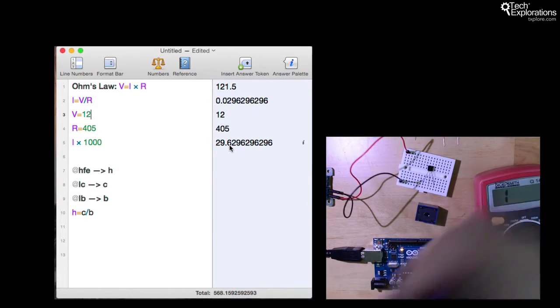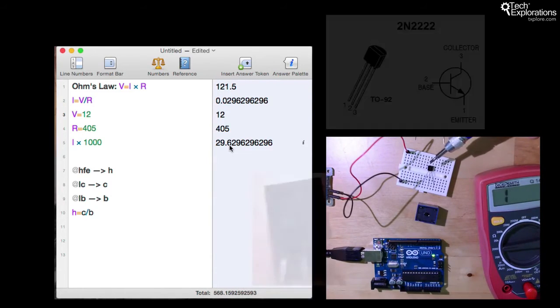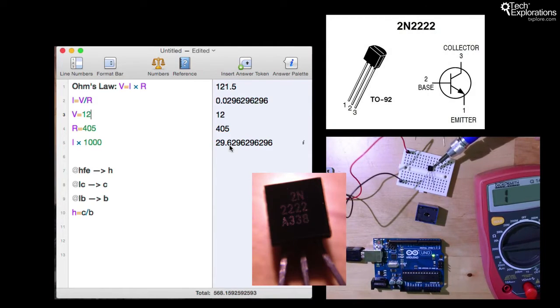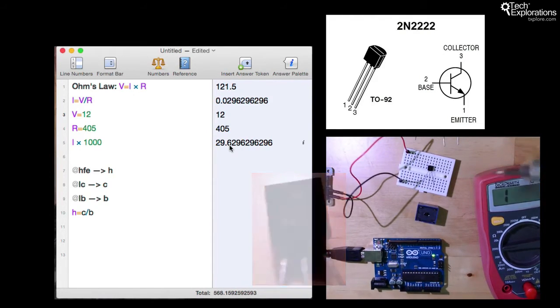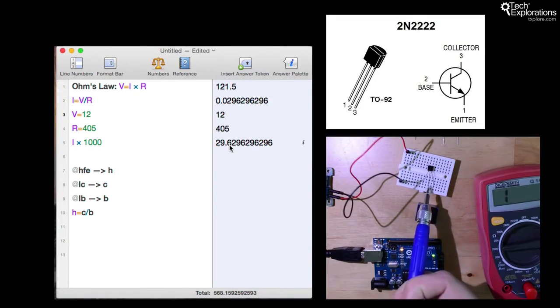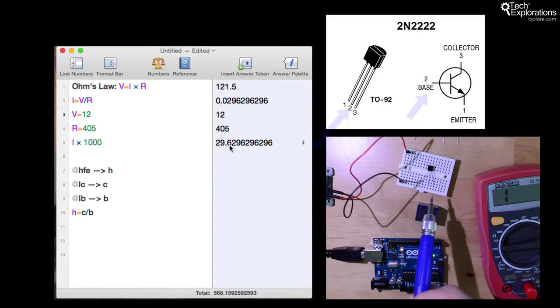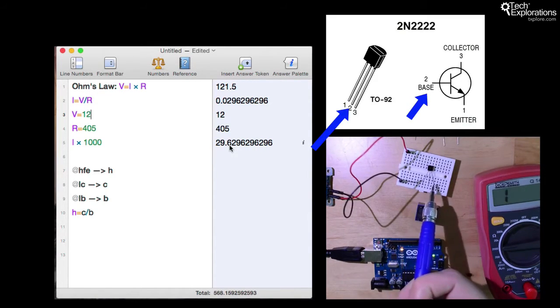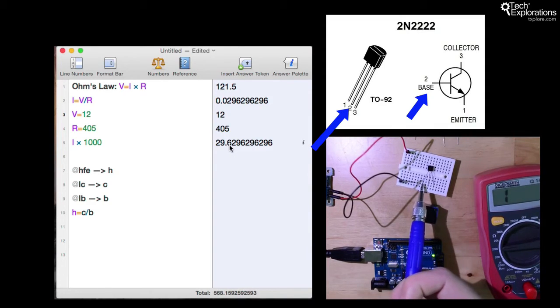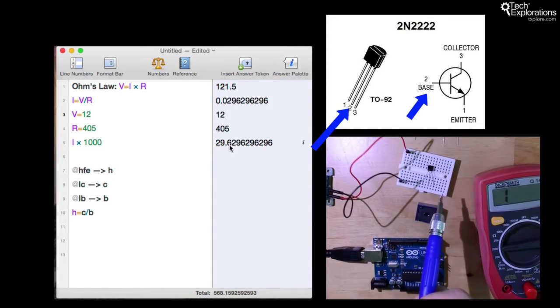So for that, we're going to use a transistor. This is a 2N2222 NPN transistor. I talked a little bit about transistors in the TIP122 lecture. And back then I said that essentially you can think of a transistor as a switch, a solid-state switch. The pin in the middle for the transistor with this package is called the base. This is the emitter on the left, and this is the collector. I'm just looking at the schematic.